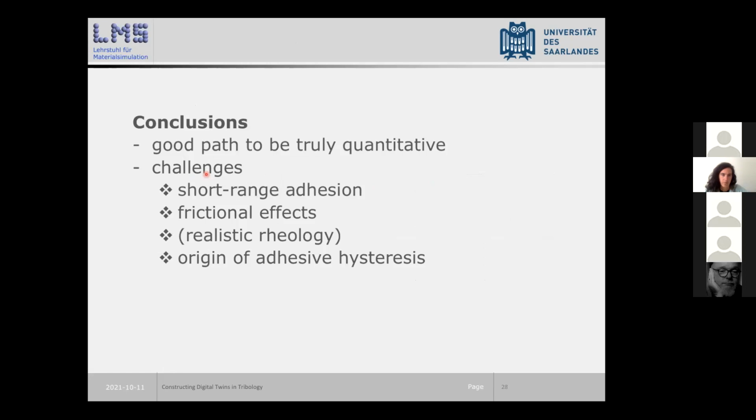One of the big challenges is to be short-range adhesive, also because the short-range adhesion dominates the dissipation at small distances, so that we get the frictional effects modeled realistically. Putting in more realistic rheology is a matter of putting in the time. And I think one thing I would like to know is if the origin of adhesive hysteresis that we often see is due to viscoelasticity or due to